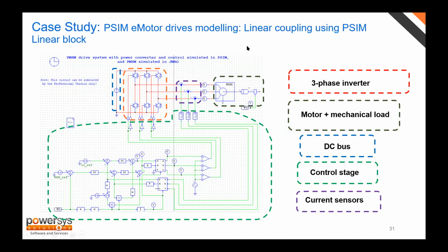Once you have filled in these basic parameters, we have designed this control strategy. First, on the left side we have the DC bus. You have the three-phase inverter in order to drive your motor, and we have done this control strategy by using basic things. In fact, we will measure the current.